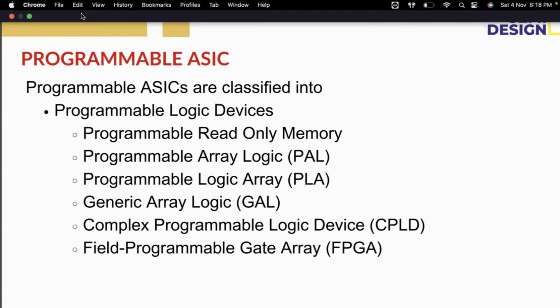So the permanent chips being manufactured are nothing but ASIC chips or SOCs. While manufacturing these, there will be continuous changes. We cannot say that at one time only we'll get the correct output and no need to make any changes. So it's wrong, right? Whenever we need continuous changes, FPGA is the best solution because it is reprogrammable. We can reprogram anytime, so it doesn't take much time compared to ASIC. ASIC means once we dump the program, we cannot change it.